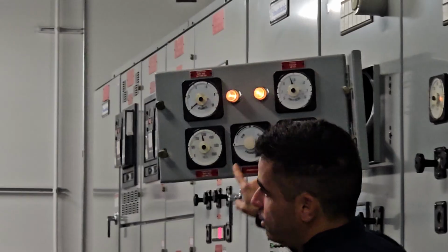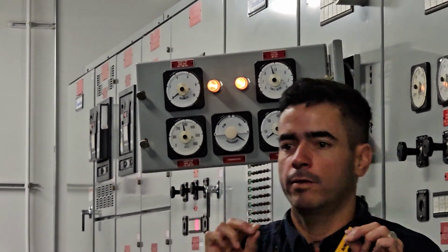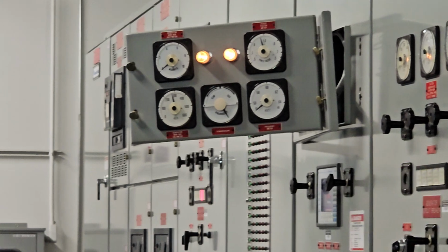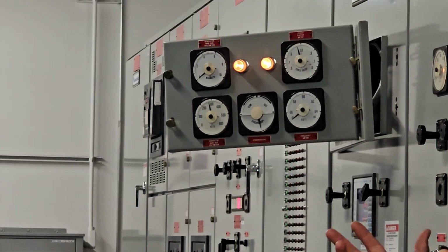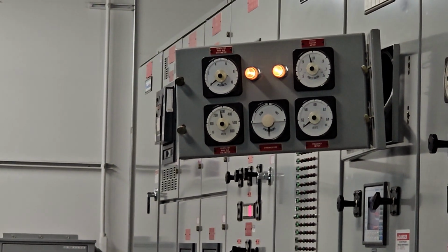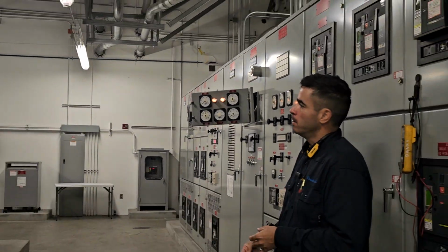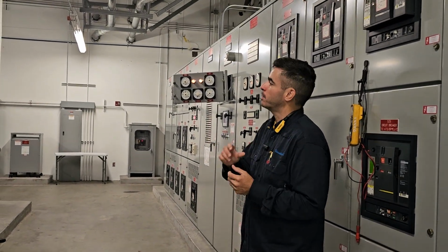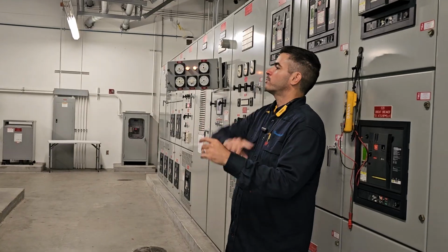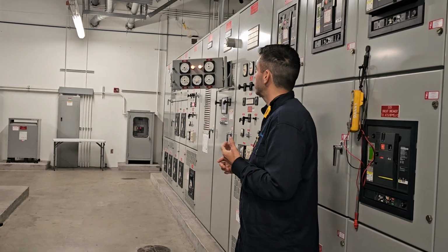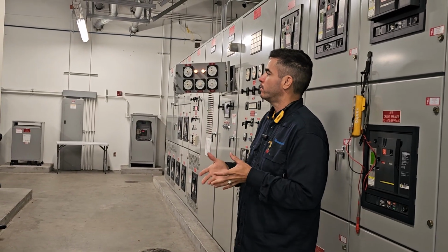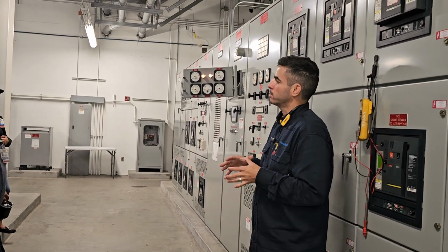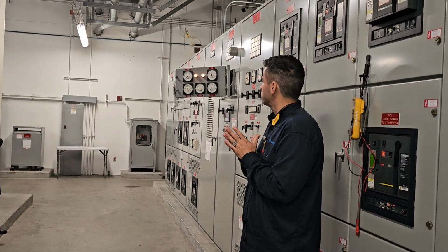Right now it's going slow because they are too close in frequency. I set this one to 60.01, I set that one to 60.01. That is fine, because the system would automatically drive them to the right spot. We want it to be that close. Sometimes people say, no, you have to raise one so it goes faster and it catches up sooner. Well, when you are in a manual condition, you want to do that, but the system is normally operating in an automatic condition, right? So you want to have it really close to 60.